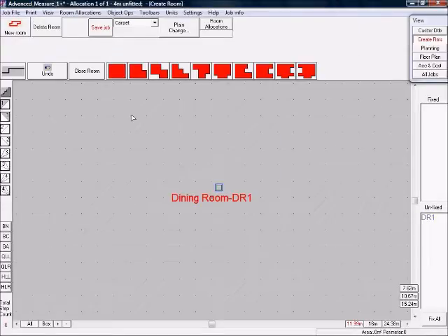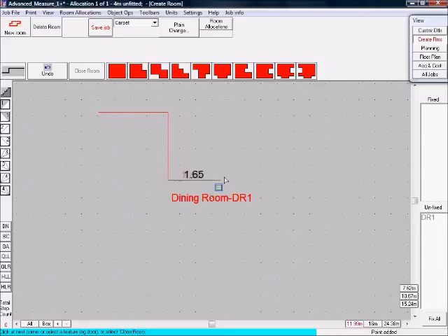So, start drawing your space in the same way as before by clicking and moving the mouse to draw your lines. We're going to stop halfway down the wall this time and draw a diagonal line by moving the mouse off center. Say we move to the left like this as though we want to draw a new straight wall. But then if we move the mouse downwards off the line, the system eventually recognises that we want to draw a diagonal, like so.